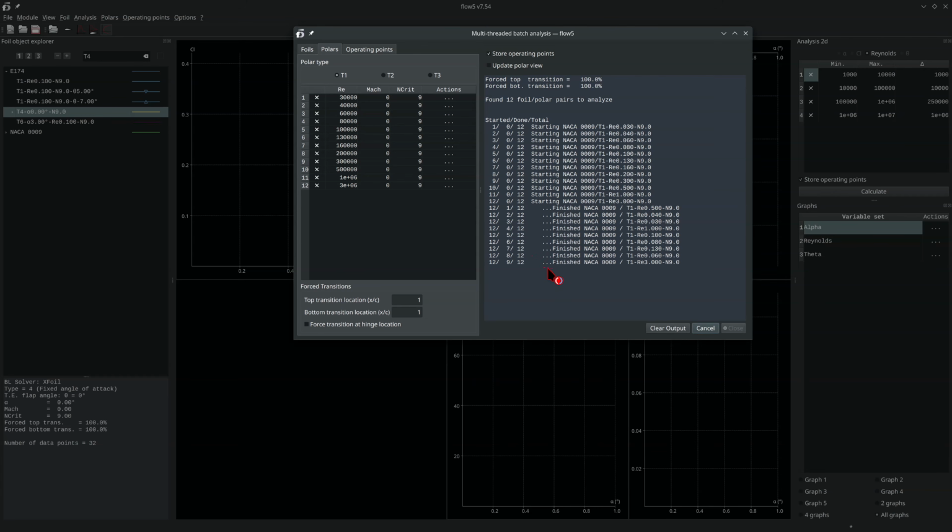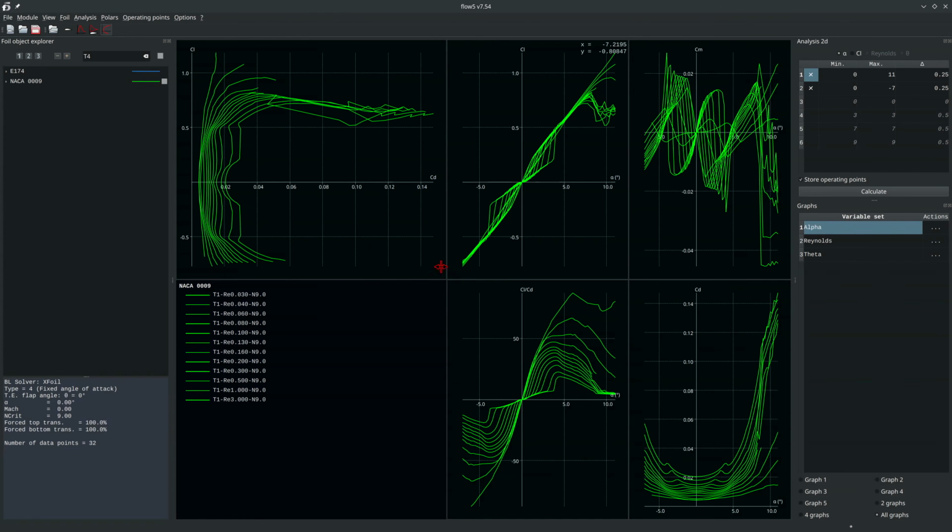If you're not familiar with the way it works and the way it is used, please look up the video I made in the XFLR5 playlist or read the documentation on the XFLR5 webpage to understand again how it works. The idea here is that instead of calculating the viscous drag each time in the 3D analysis, it just interpolates its data on this set of curves here.